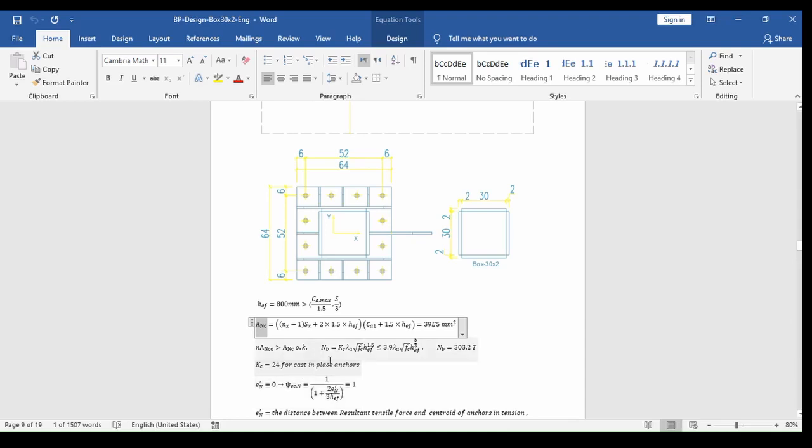And then we found that 20 millimeter as a thickness of the base plate is enough through simple equations here, but in IDEA it wasn't enough, so we increased it to 30 millimeter to meet the 5% strain limit criteria. So it is, for example, a 30% difference.